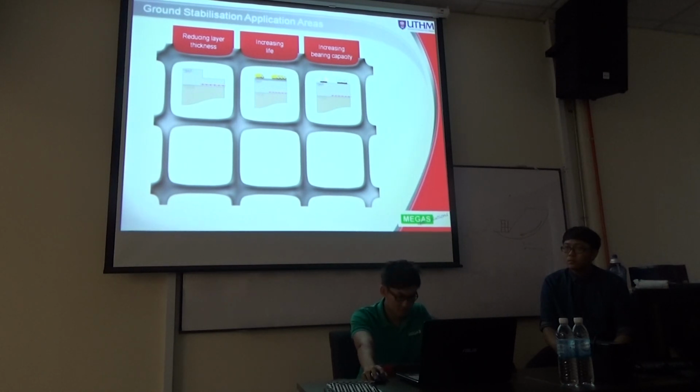So if we are able to increase the load spreading angle, we have a bigger A subject to the same F. So what will be the stress? Smaller. Because A is bigger and F is maintained, the stress will be smaller. So in that sense we are able to increase the bearing capacity, because for the same stress, we can apply more force onto the widened area. So that is how we can increase the bearing capacity. Okay, can follow?